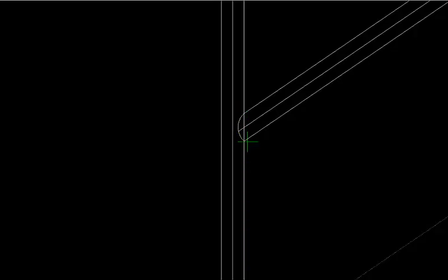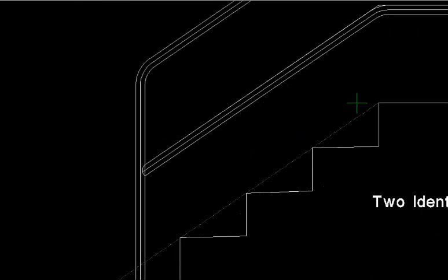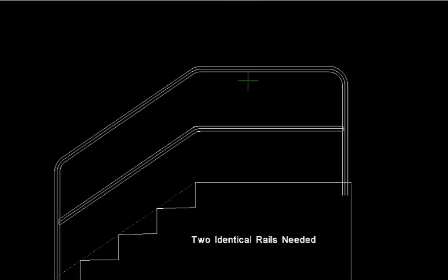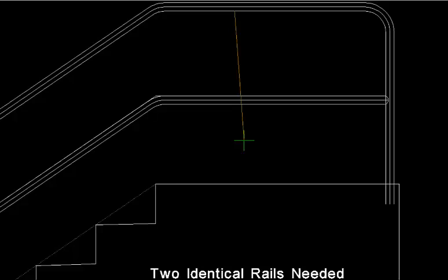You end up almost not cutting the bottom part of the pipe here. And it seems to work out pretty well for us. We still leave it as a half in most cases, unless it's a very, very steep set of rails. And sometimes you'll have to go a little deeper on the notch, but you'll see it when you draw it.